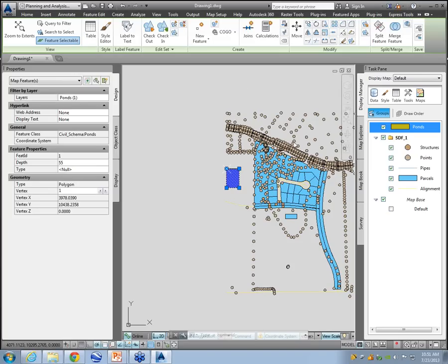You grab a bunch of objects and you try to do that, guess what happens? Again, I don't know why they programmed this. It's going to grab each one object one at a time, check it out, add it to the cache, make the change. Go to the next object, check it out, add it to the cache, make the change, etc., etc., etc. You get past about 30 and you're going to get really bored and you're going to get to kicking your computer. So, a lot of objects, check them out first, then make the edits.